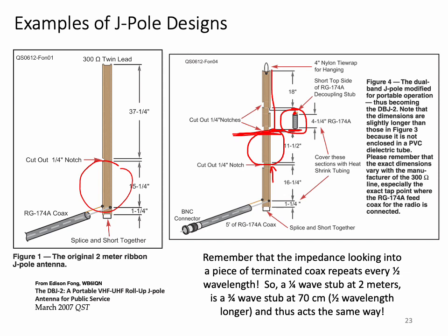So at this point, at 70 centimeters, this little stub acts as if it's an infinite impedance. So when I operate this antenna on 432, the 432 energy doesn't see any of what happens above this particular stub because it's choked off by the high impedance. But if I operate on 2 meters, this portion operates as part of the 2 meter antenna. The quarter wave stub for 70 doesn't look like a stub anymore because it's no longer near quarter wavelength, so it acts as a piece of wire.